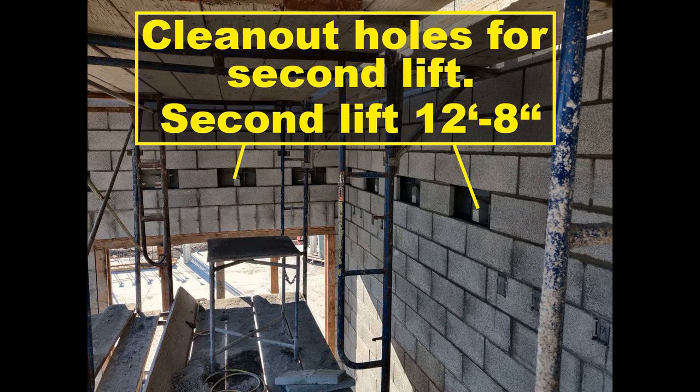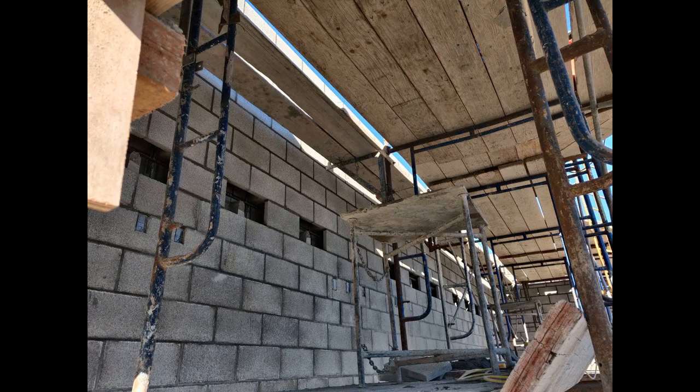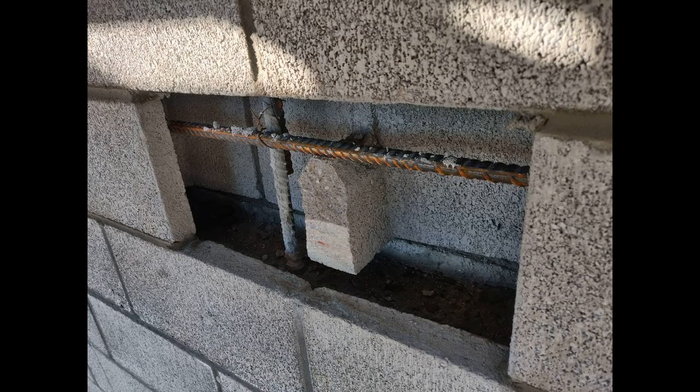Provide cleanout holes at a maximum spacing of 32 inches where all cells are to be filled with grout. Establish a new series of cleanouts if grouting operations are stopped for more than 4 hours. Provide cleanouts not less than 3 by 3 inches by cutting openings in one face shell. Manufacturer's standard cutout units may be used at the contractor's option.